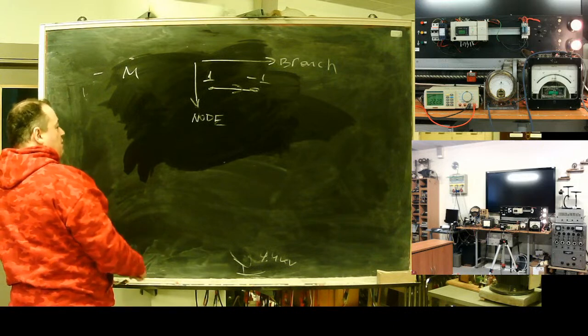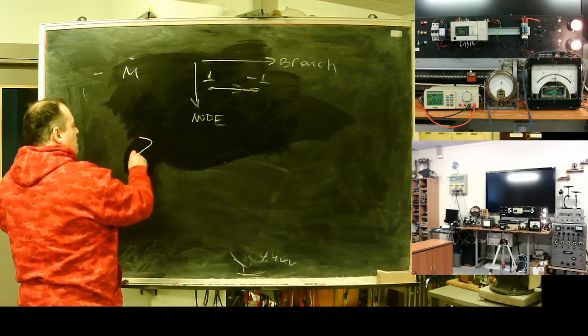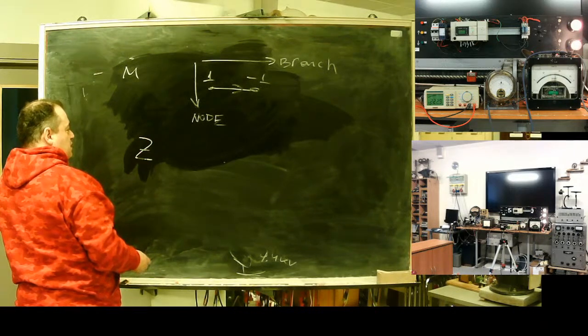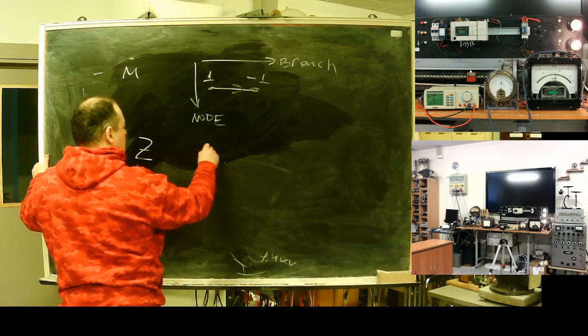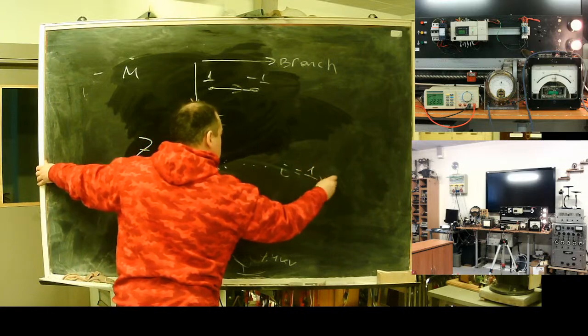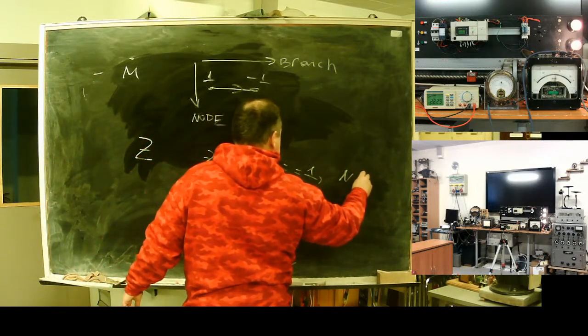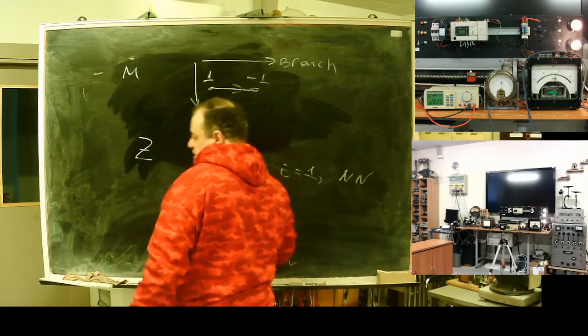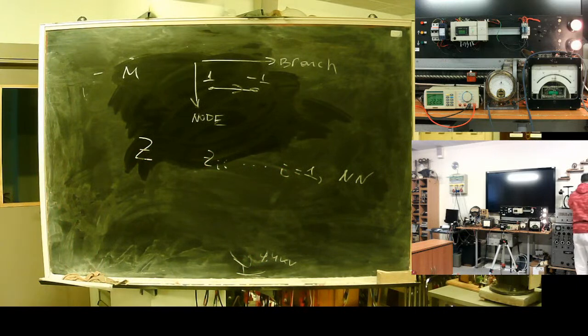Branch resistances, lines and transformers, are in the resistance matrix. Actually, we will fill only the main diagonal, from 1 to the number of nodes. We should not take inductance into account for load regimes.